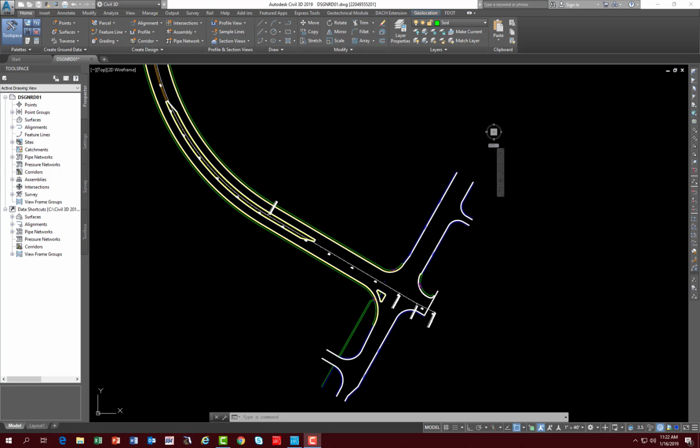Using the append function in EMX will force the target line type to take on all of the settings of the selection you make in EMX. In other words, it will change a line type, layer, color, symbology to the FDOT standard along with the appropriate X data that will then QC and also quantify in reports. For detailed information on EMX, please refer to Chapter 2 of this manual.